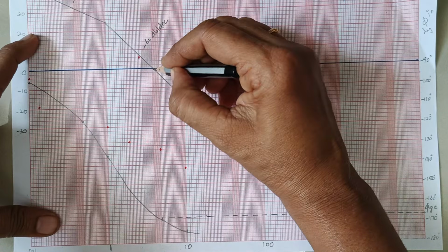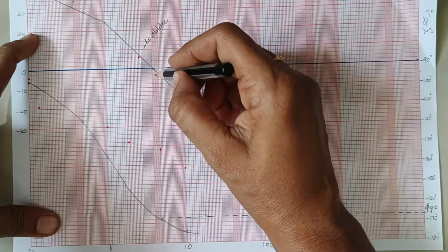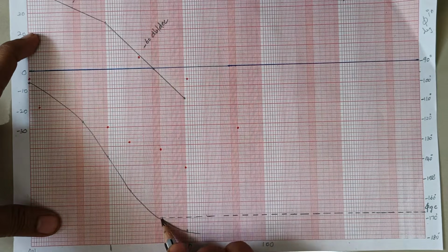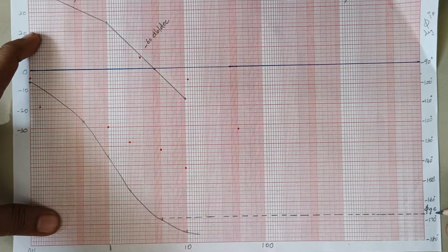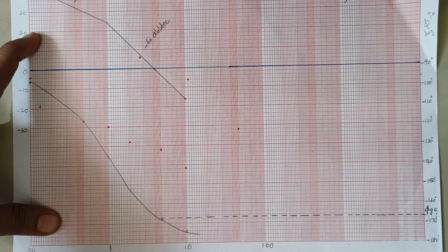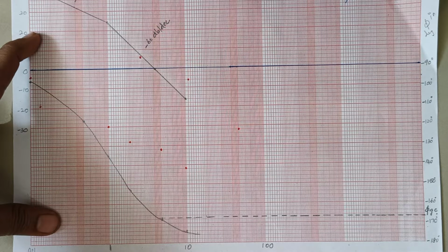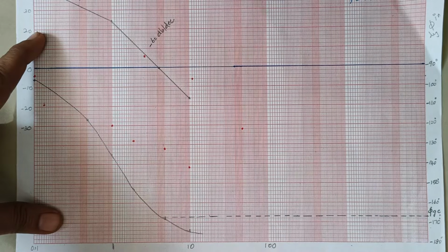magnitude plot crosses the 0 dB line at a particular point. When you draw a line from this point, it will meet the phase plot at some other point. At this point, just measure the angle. This is found to be 167 degrees. Even if you get 1 degree less or 1 degree more, that is plus or minus 1, it doesn't make much difference. So here the phi GC value is 167 degrees.